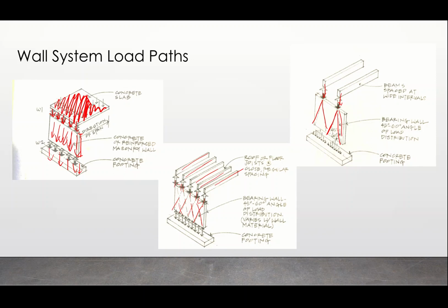Okay, so when it's hitting there, as you can see, that is not a uniform distribution as it's hitting the footing. It's more linear in shape, coming maybe at 60, 45 degree angles, whatever the case may be, however they designed it, not uniform for the footing, all because the loading is going to two beams that are not equally spaced out on the wall. Okay, there may be some gap differences between there and there.